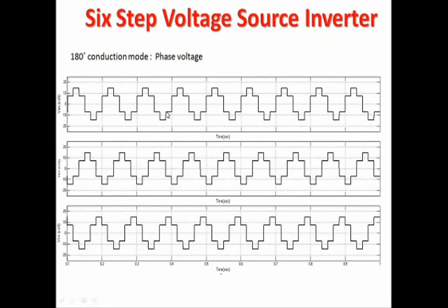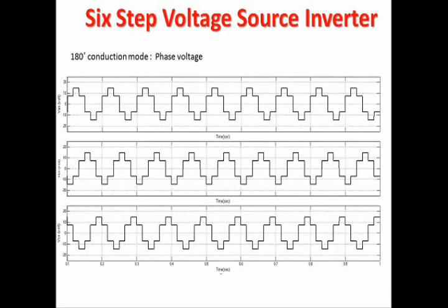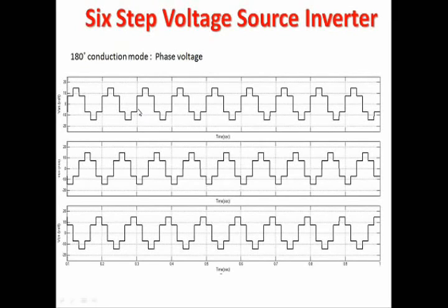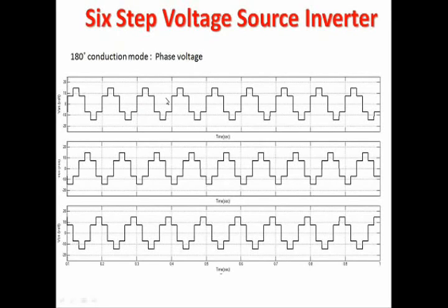Because we are going to switch on the 6 switches sequentially, 6 steps will be produced in the phase voltage. So for this reason only, the inverter is called a 6-step inverter.